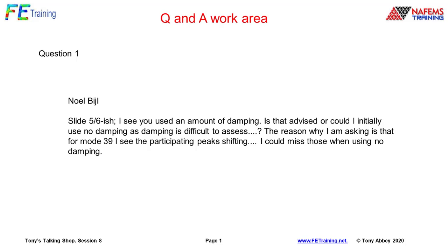So I tend to want to put in a small conservative value like 2%. And then for transient, again, I would tend to put in a level of damping, typically 2%. It just stops resonance giving very, very strange results. That's the reason why I do that.